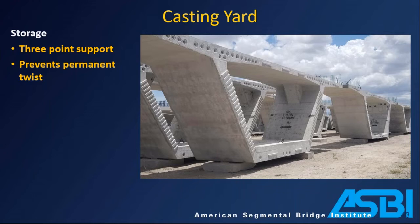And in this case, it's not the rocking that's an issue, but it's the fact that since concrete creeps over time, it'll start to try to twist to set itself down on that 4th support. And then when you fit them together in the field, they won't fit together as well. So you always want a 3-point support, one under one web, 2 under the other, to prevent that twist from creep.